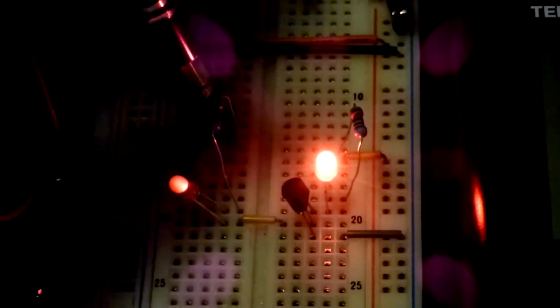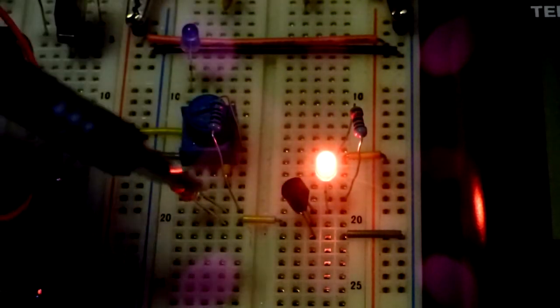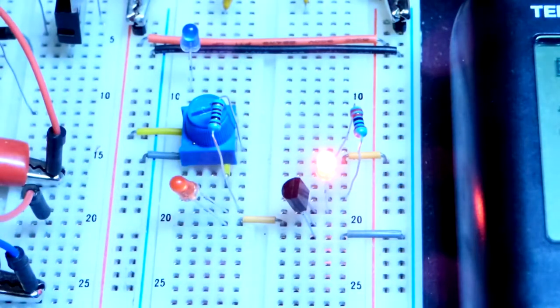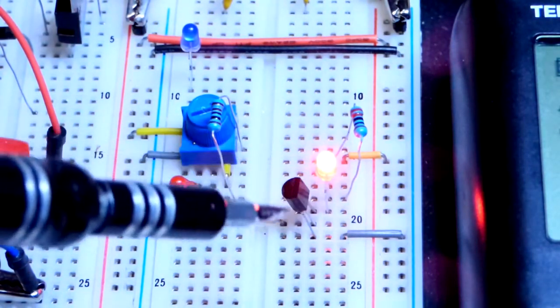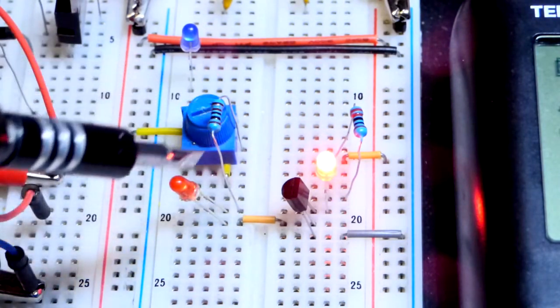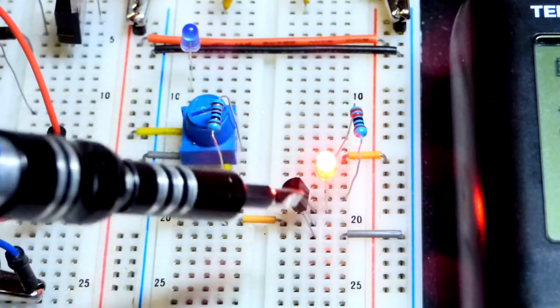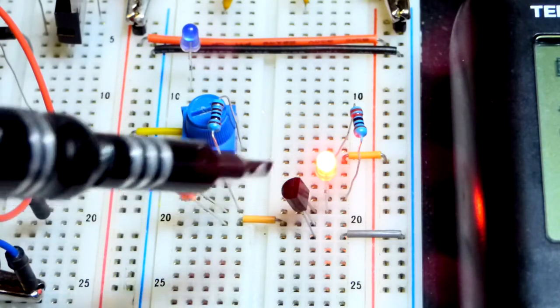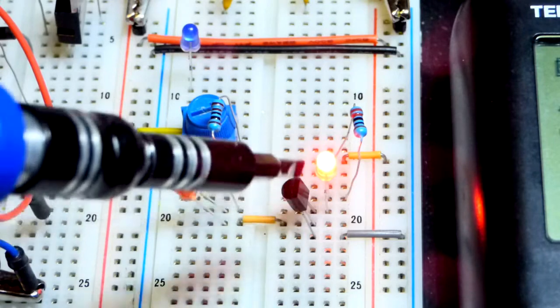It's an amplifier. It's taking the current that we are putting there, and it's giving a multiple amount. Since it's a 2N3904, whatever we let through here, let's say if it was a milliamp, this will probably let through 200 or 300 milliamps. So this is lower, but the main takeaway is probably about 200 or 300 times.